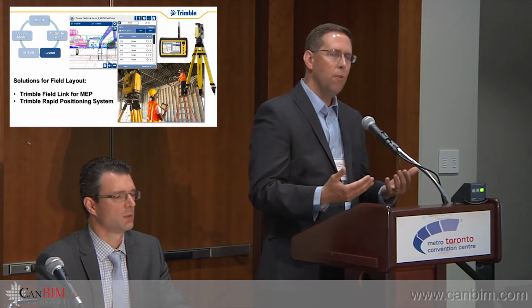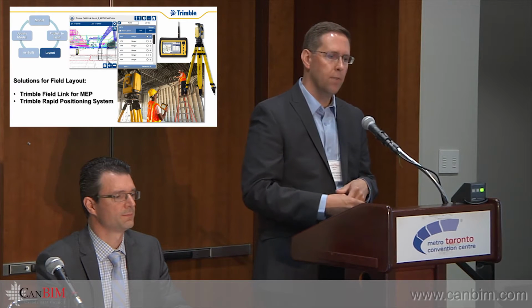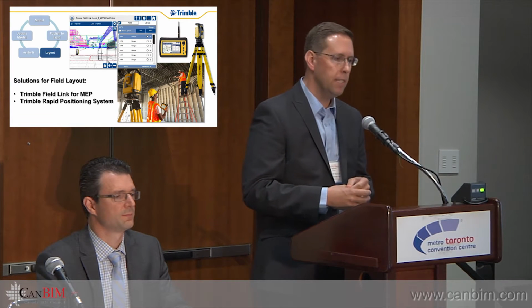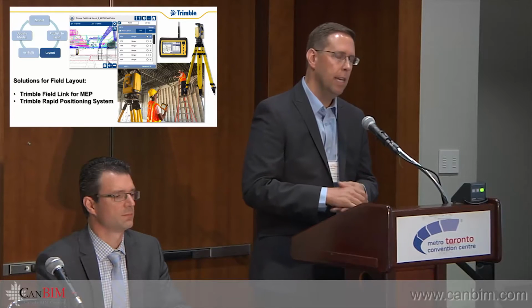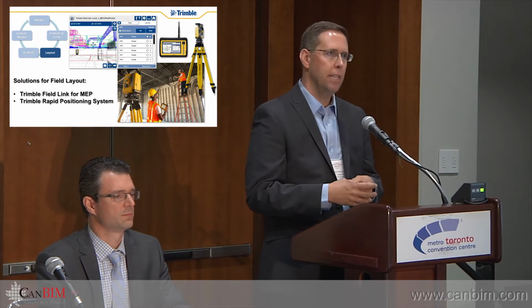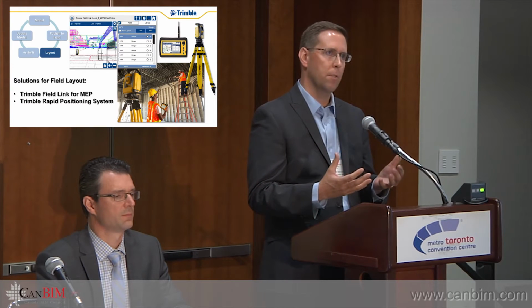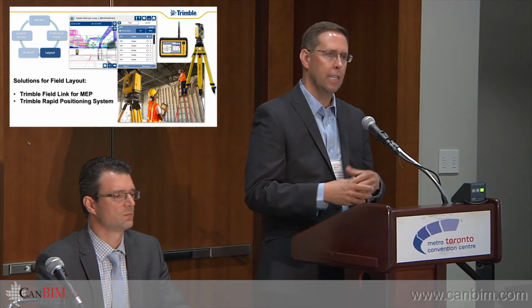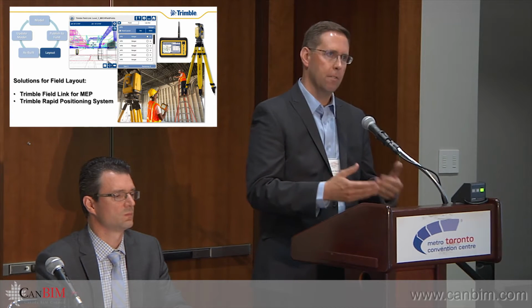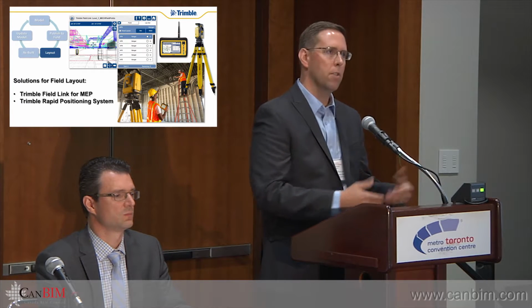So then once you have your points created for layout, then you can do the actual physical layout on the job site by the trades. And so for those solutions, Trimble offers the Trimble Field Link for MEP system and also our rapid positioning system. And these are robotic total stations that are now taking that 3D model information that you've created in the office, putting it on a controller out in the field, and then that controller is guiding a robotic total station to accurately lay out the information that you've created in the model out into the field.